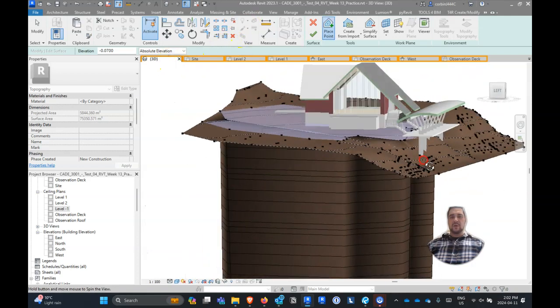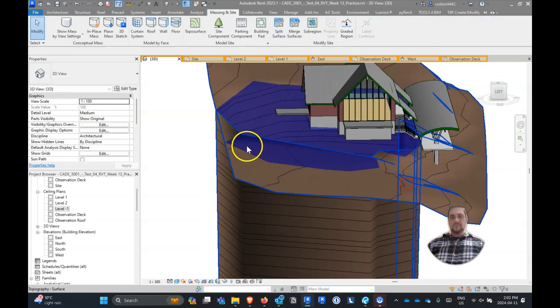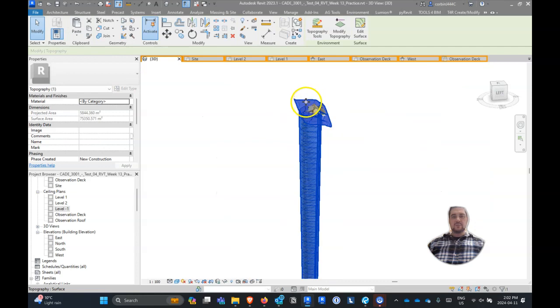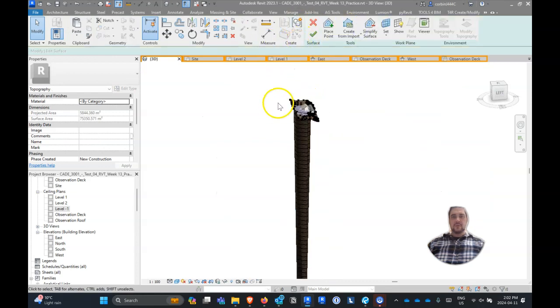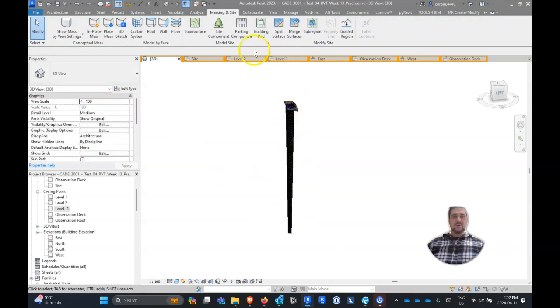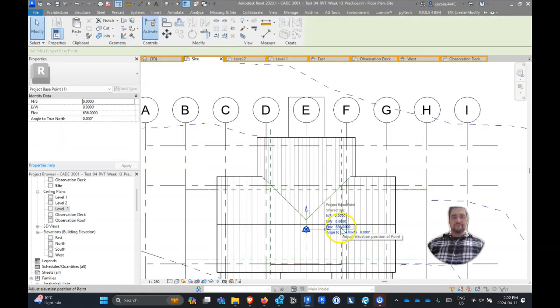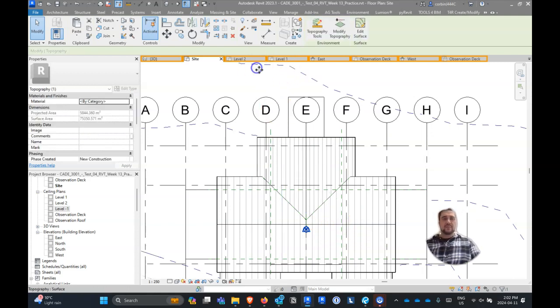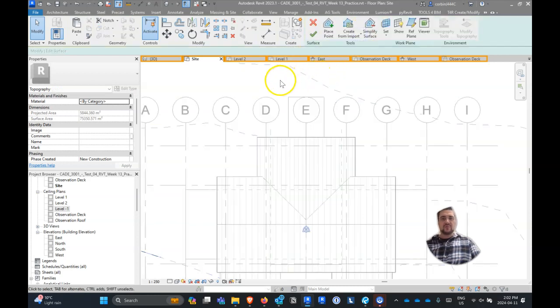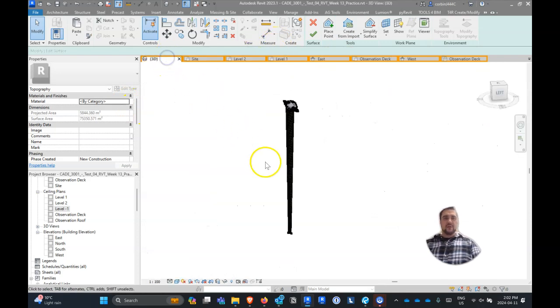And so now our topography is going to look like this. And what did I do? Did I do negative 70? It makes no sense. Did we raise our project base point? I don't think we did. It is raised. Cool. So we need to adjust something. So let's go here to Edit Topo Surface, and let's find those points that we put down there.